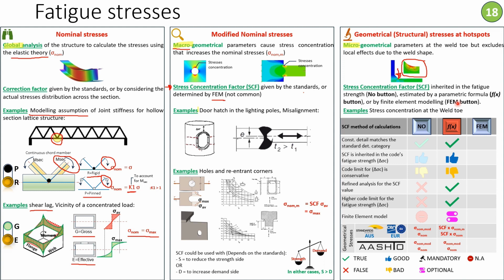Finally, let's talk about finite element modeling to calculate the stress concentration factor. You resort to this when your connection does not fit within the testing range conducted by the code. In that case, doing finite element modeling is mandatory. And again, because you are doing refined analysis to calculate the stress concentration factor, you are still eligible to use the higher fatigue strength provided by the code rather than the conservative value.